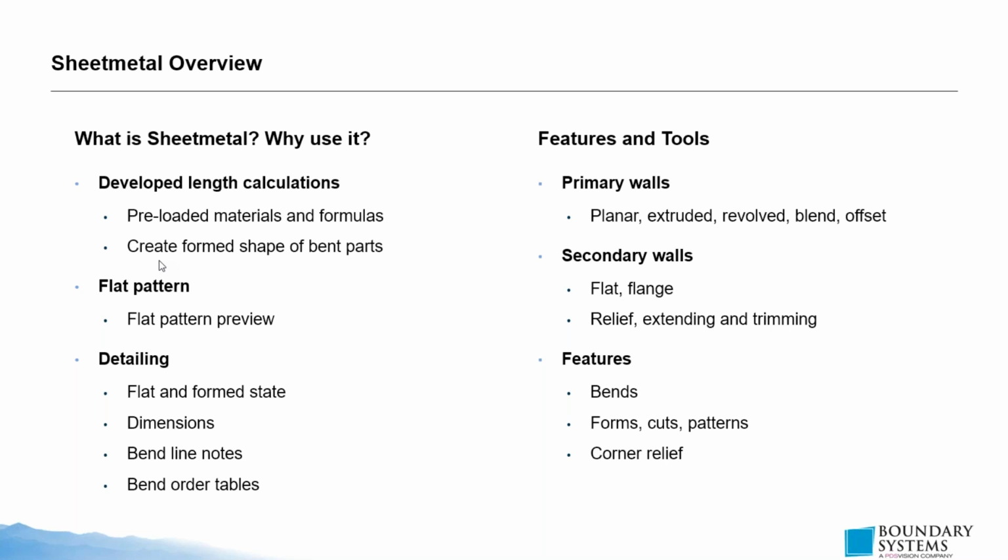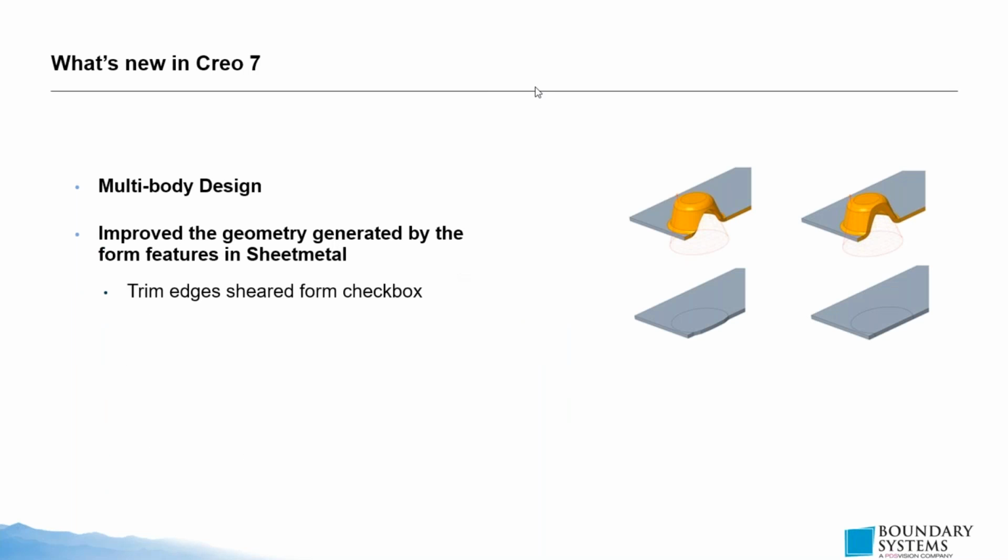And lastly, you can modify corner relief. You can customize how the material will be distributed between two different parts of a corner, how it will fit together, if it will be rounded off, etc. So that covers essentially the basic design process and how Creo Sheetmetal works.